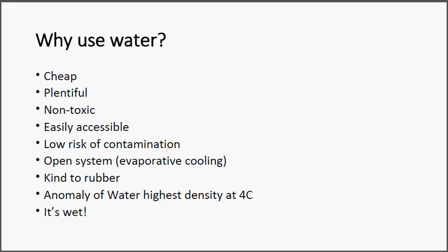So yeah, that's again, it's an advantage. So it'll settle down. It'll always go down. Cold water is going to go down. Hot water is going to rise. And the beauty about that is that you can use it for cooling, for natural convection. So you don't have to have forced convection in any sense whatsoever. You just have a pipe system, and you know that the coldest water is always going to be at the lowest point.